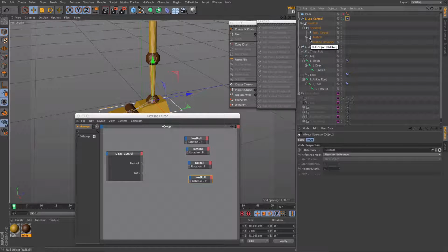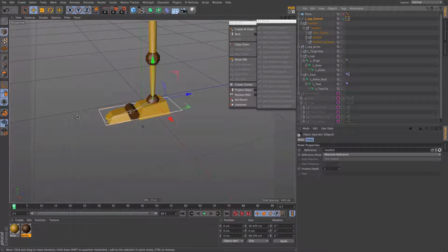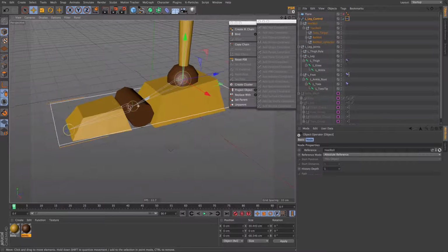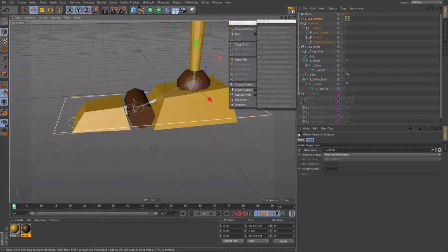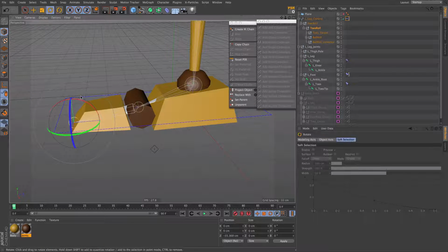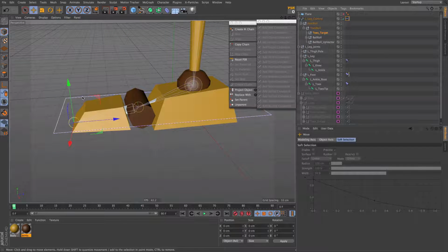Oh, there is one thing I forgot actually. One more thing that we will want is to control the joint, the toes rotation as an FK, right? And I made all the IK here, but I forgot the FK. And this is why we want a different object as a pivot for our toes and as a target for our toes.